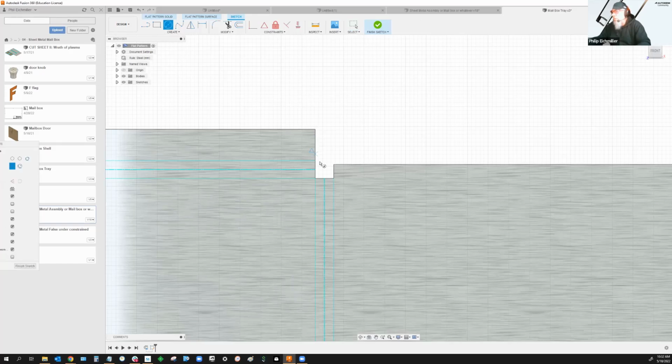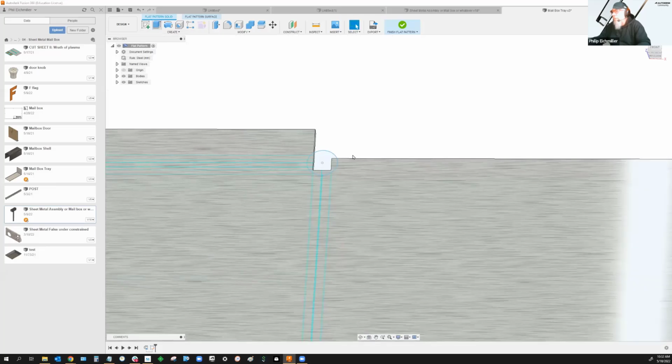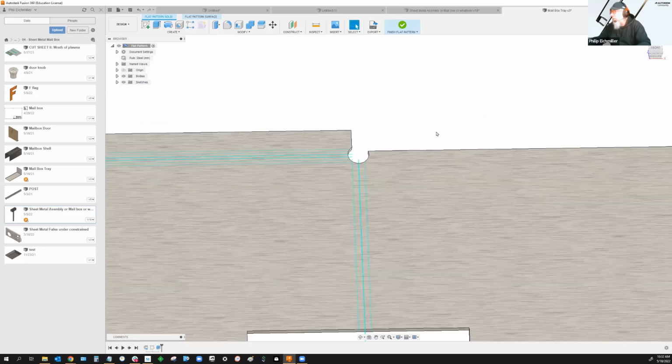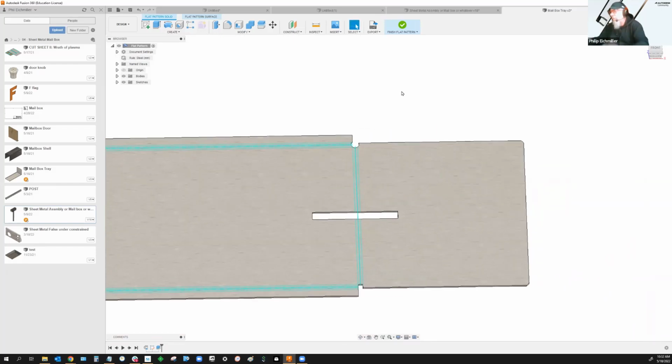So maybe I need to just, for this instance, put in a manual relief. I'm just making up a size here, but I'll manually create the relief that will make the laser the happiest, right? So now I can go cut this thing, run it through my contouring and get the laser happy with it, and finish the flat pattern.